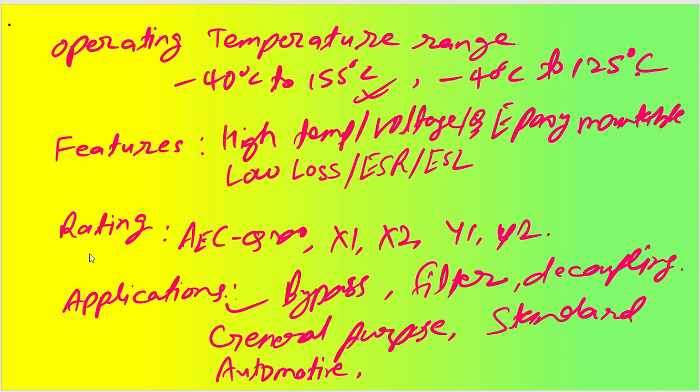Now come the ratings. As you can see, it may be mentioned or it can be blank. Generally AEC-Q200, or X1, X2, or Y1, Y2. All these ratings, X1, X2 and Y1, Y2, are used for safety purposes in SMPS.